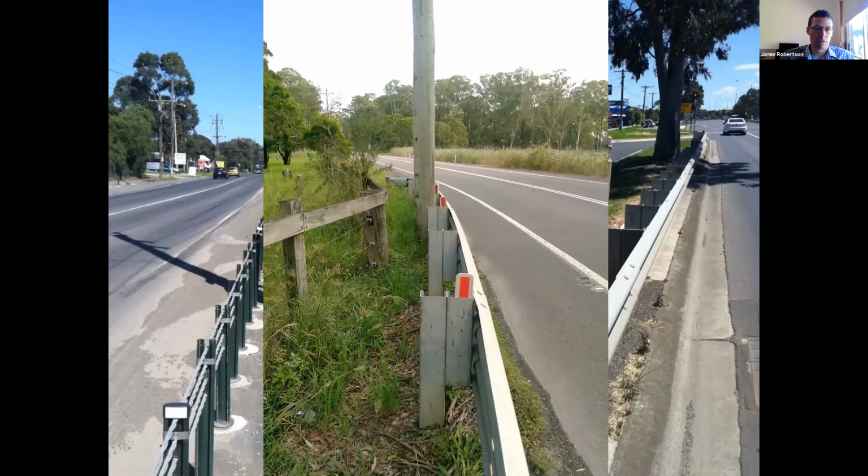An effort has been made to stiffen it up. There are also other hazards in advance of this point that are adequately shielded by the barrier. So I guess the moral is, where we don't have adequate space for deflection, think about your choice of barrier product, choose one that deflects by less, and think about measures to reduce its deflection further, particularly reducing post spacings.